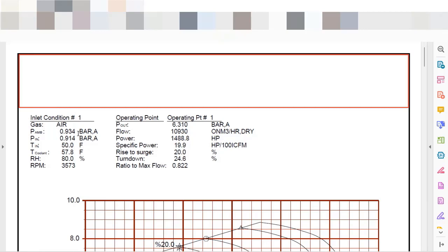As I mentioned to you, we develop the heat and material balance, and transfer the results that are of interest for the equipment to a process data sheet, and other disciplines add information to a specification data sheet so that we can do the quotation of the equipment and eventually the purchase of the equipment.